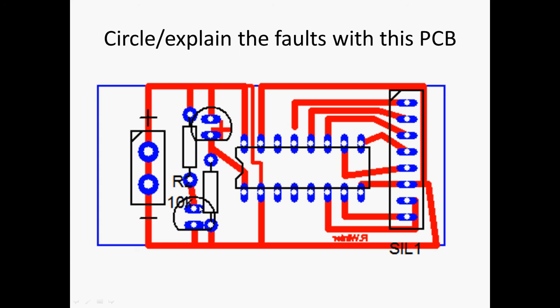Here the two components are physically overlapping, so when you put them on the board they wouldn't share the same space. This is bad practice. You shouldn't really put a very thin track through the middle of this, particularly not at school anyway, because our equipment can't etch circuit boards to that quality. In general, there's a lack of labels. There should be far more component labels.